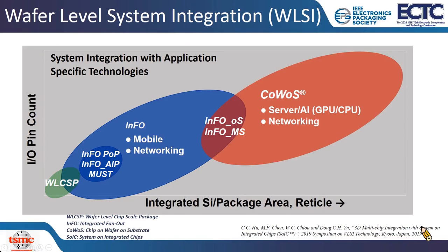However, the I/O pin counts of the conventional flip chip stacking have been limited by the bump size, which is difficult to scale beyond 10 micrometer pitch. Furthermore, the interconnection of scaled micro bumps with underfill may increase the parasitic capacitance, resistance, and inductance, and may degrade the device and power performance.